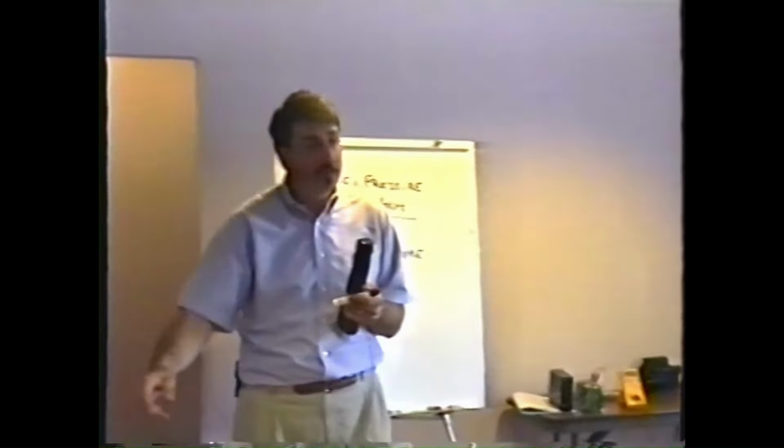Let's say we have a resistor that is, let's say, blue is the first band, and green is the second, and red is the third band. Forget about the fourth band for the moment, the gold band. We'll start with the other side. Well, how many ohms is this? Let's see. The first band is blue, so that's 6. So we'll write down the number 6. The second one is green. Green is 5. Write down the number 5. And the third band is red. That's 2.